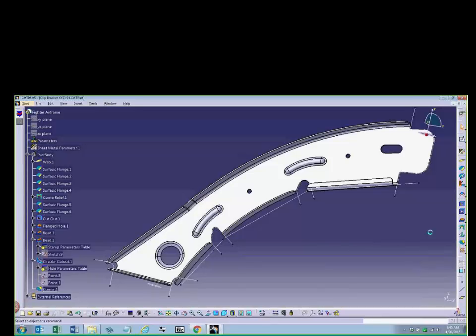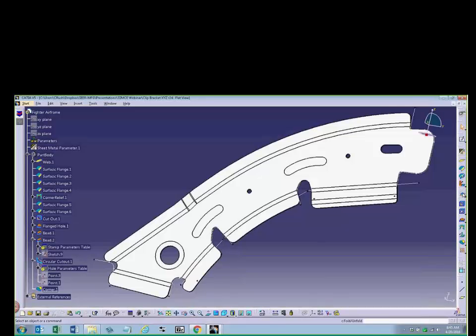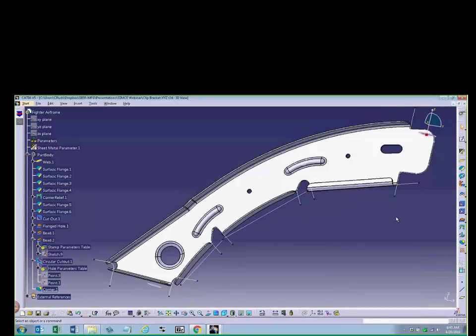within CATIA. So the sheet metal interface itself, going into a bit more detail, works with the aerospace sheet metal design workbench, or the generative sheet metal design workbench. The part design must contain what they call a web or a wall feature that determines that we're working in what's called the sheet metal type module in CATIA. When you're working in that environment, you can flatten the part and fold the part to see the start, flatten shape, and so on. So we've created interfaces to all the sheet metal operations within SEER-MFG that Joe mentioned to you. And there's much more because we include elements of tooling, drilling, and all the detailed finishing operations.